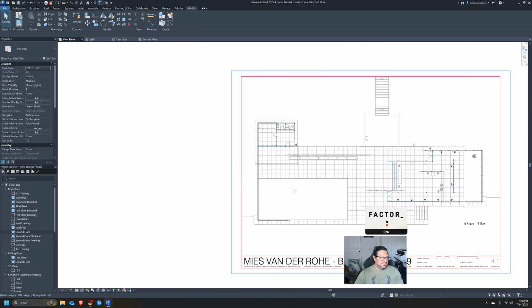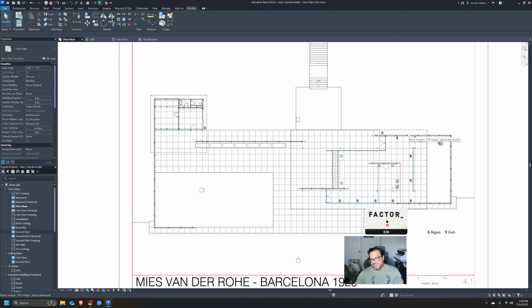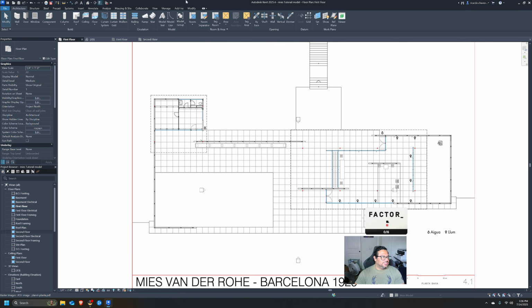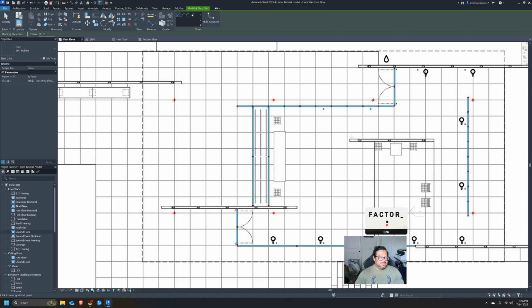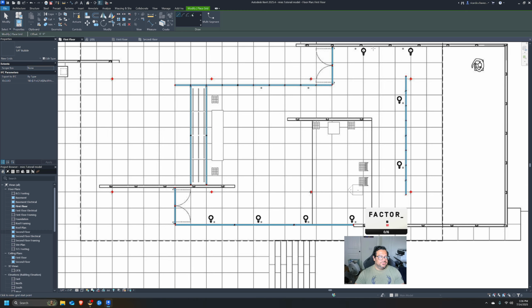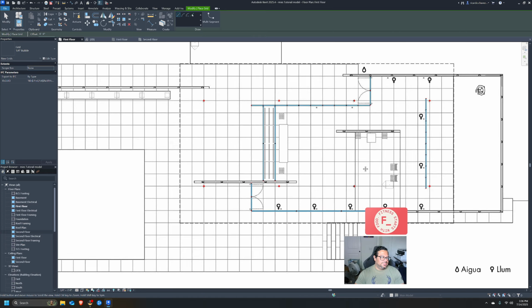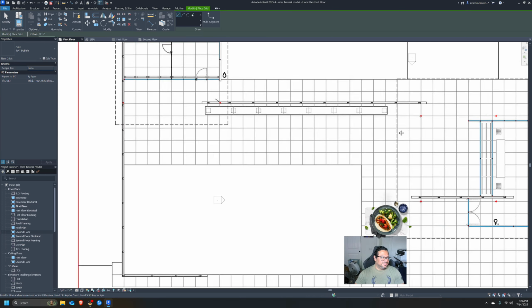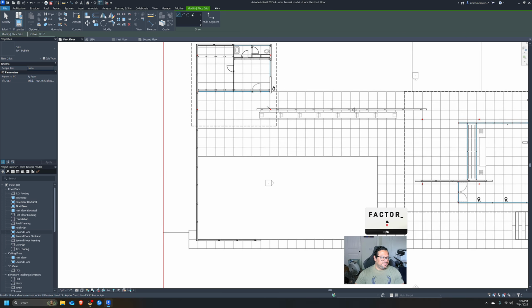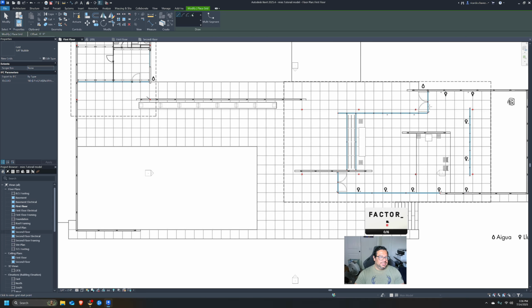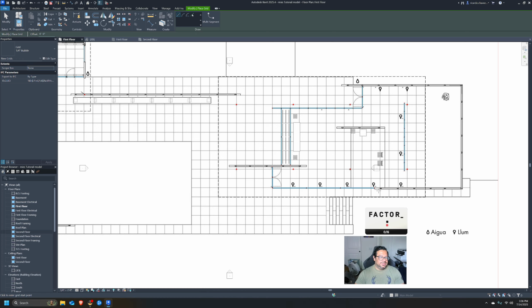Let's put some grid lines. Every project is going to have grid lines. You're going to work with your architect, your engineer, etc., right? If you go to Architecture, Grids, you'll see that you can start placing grid lines here, and this helps with column placement. So here you see we have 1, 2, 3, 4, 5, 6, 7, 8 columns. So we have 8 columns, and then we have some structural members over there. We'll keep it simple. We'll just do the columns here.